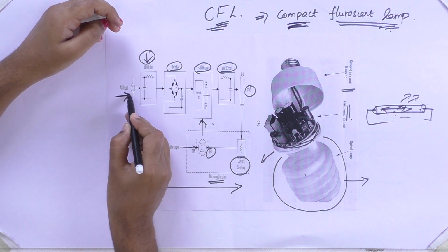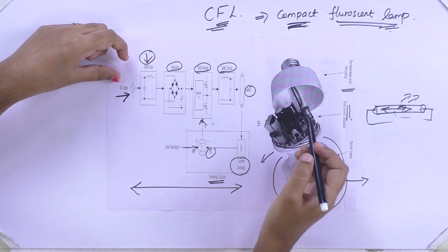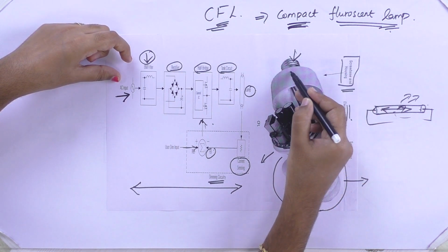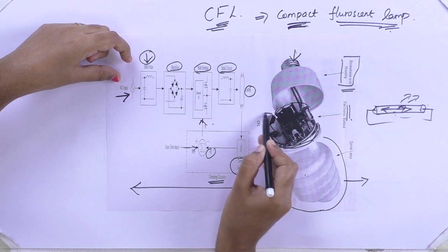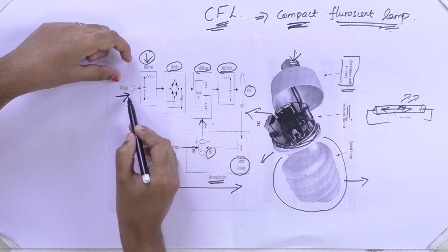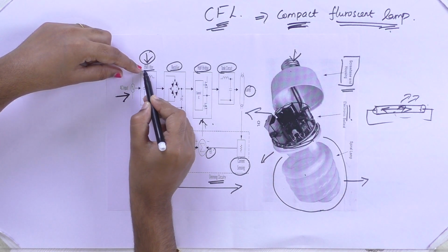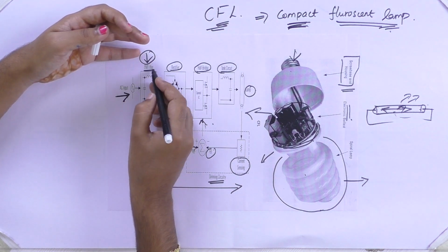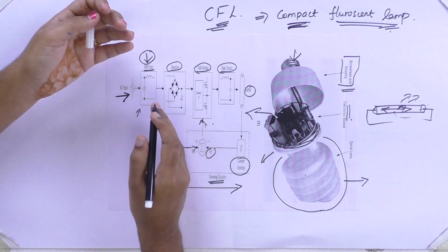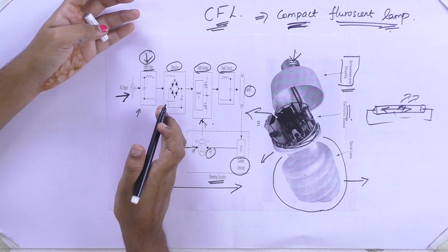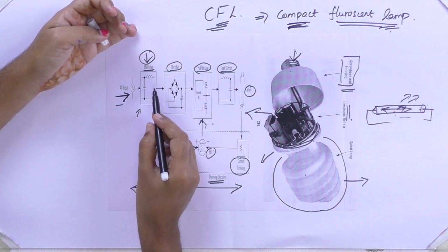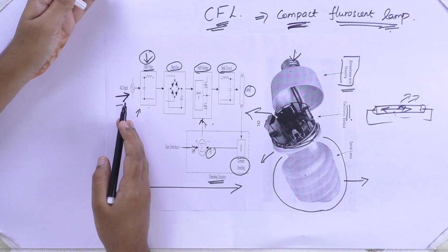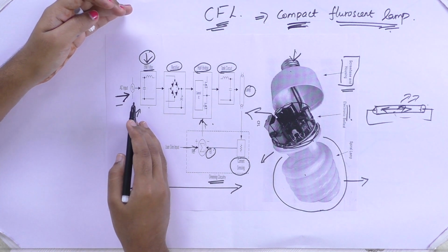See, we are supplying AC input through this housing. Here, this unit consists of these blocks. You will have an EMI filter, that is an electromagnetic radiation filter, here to avoid the resonant or varying voltage on the input side. We are using the EMI filter that will filter out the supply voltage and it will be given to the rectifier.